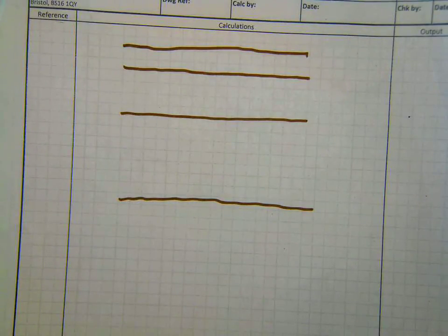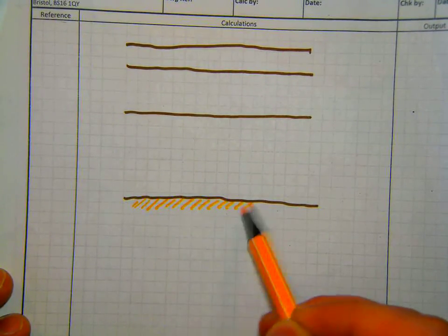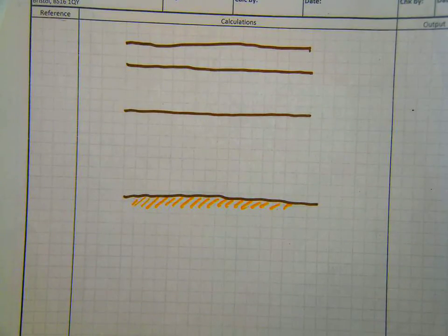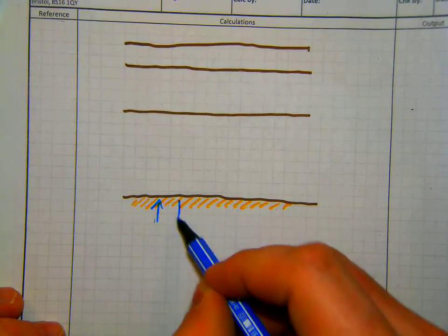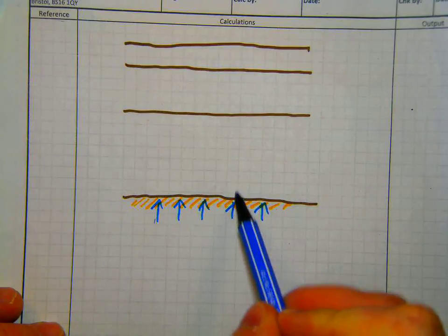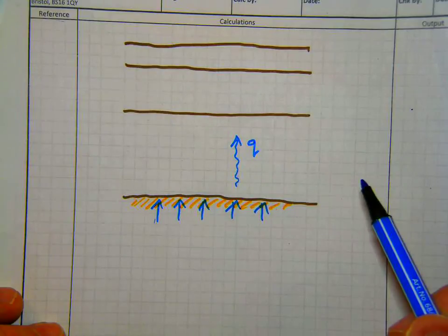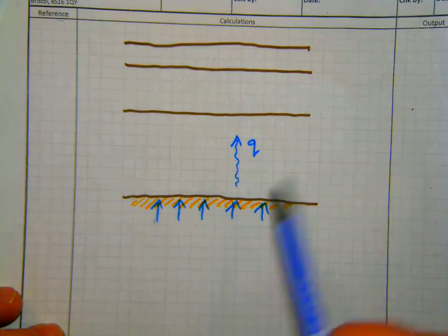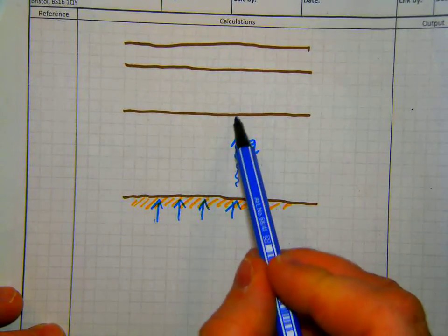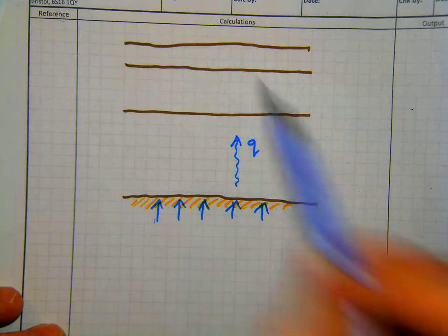We're looking now at the second part of this question, where we've got our same scenario. We've got our aquifer, that's made up of a gravel bed, and in there's this artesian water pressure. So there's a pressure in this gravel bed, and that pressure there is causing an upward flow of water at a certain rate. Now, whilst the velocities might change as it goes through different permeabilities, the flow rate will be the same flow going all the way up through.